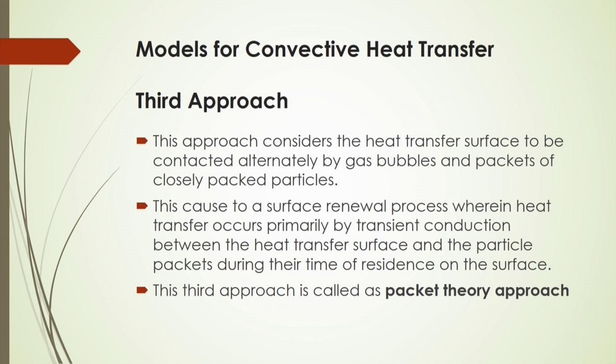You will see it is very interesting that on the bubble surface, there will be some packets of particles depositing, and those packets may change their position from the surface to the emulsion, and again from the emulsion to the surface. So every time there will be a continuous contact, meaning packets of particles will contact the bubble surface.